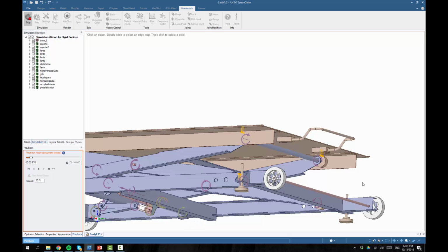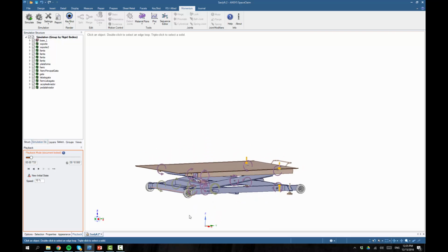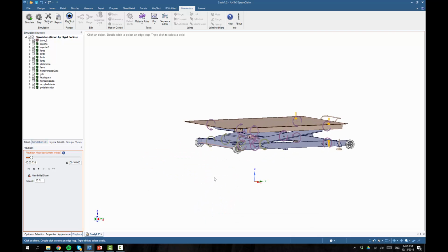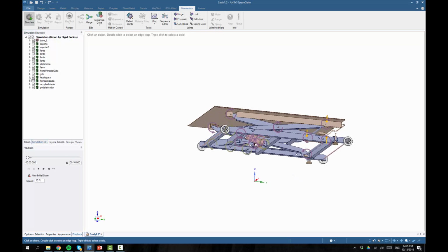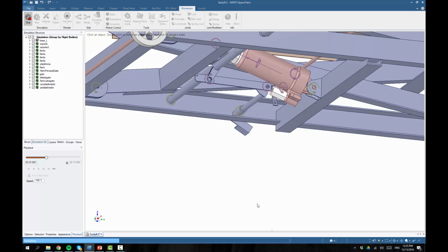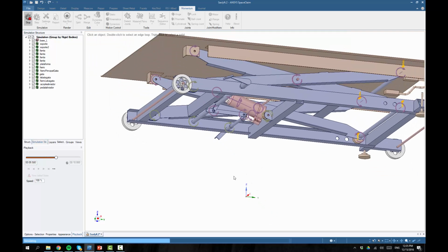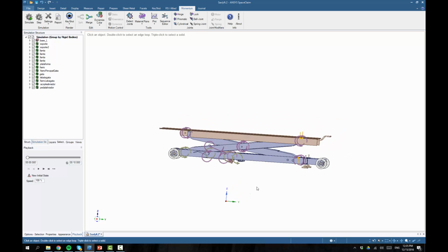Okay, but let's say that we want to run our next subsequent studies from this starting position. I just click New Initial State, and next time I press Simulate, the simulation will start from this new position. Let me just go back to real-time playback, like so. And we can see how these things are still flopping around like that because they remember the motion from the previous simulation. And obviously, if you want to, you can go in and modify all these initial velocities to whatever initial state you want.